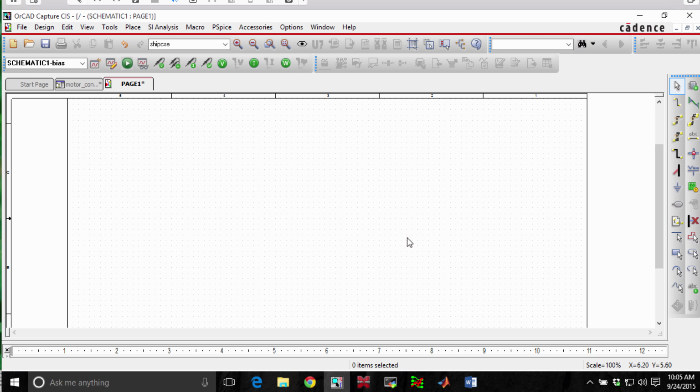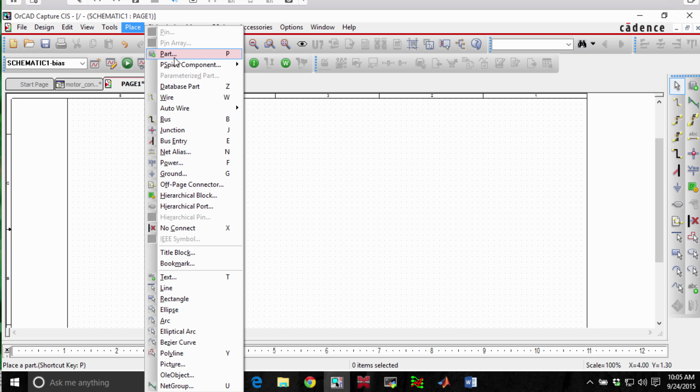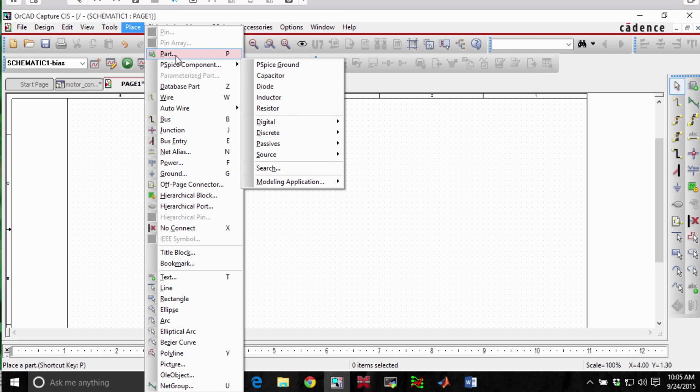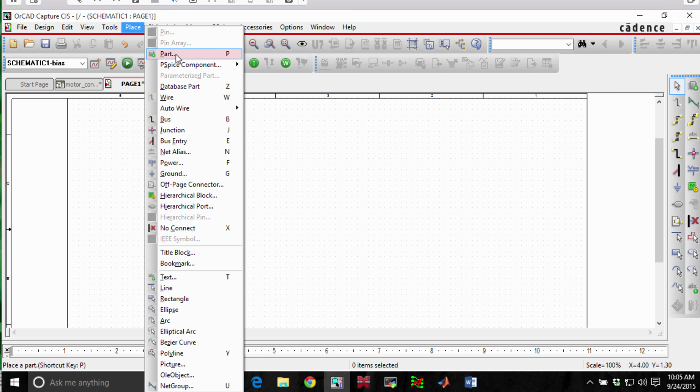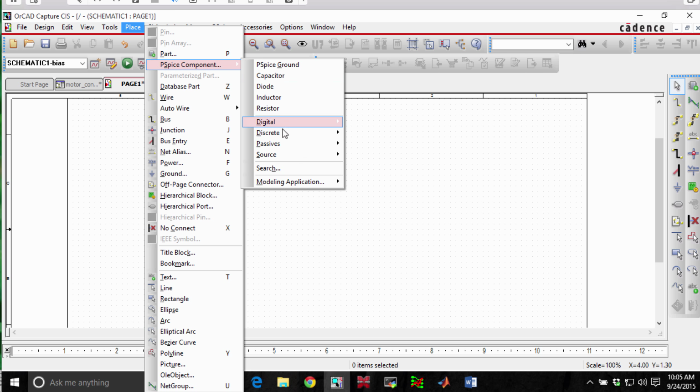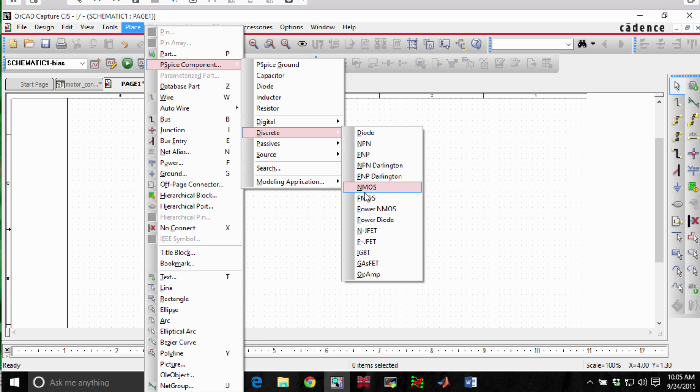The next thing we need to do is actually start placing the parts. Now, we're not trying to build the PCB directly yet. At this point, I'm just going to use some generic parts. So, for instance, I'm going to place the MOSFETs first. Although I could do a part search and see if I can find an existing, exact match for the MOSFETs that we're using, I can just use generics. And for now, I'm just going to go ahead and use generic parts.